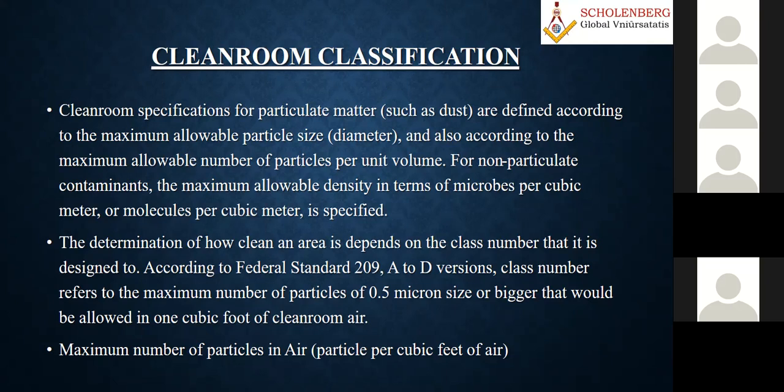We have designations, like for example, when you come to refrigeration, we have a refrigerant. How do we have a refrigerant number? We have a certain prescribed designation formula. Like if you see R11 or R12, basically it is a chemical formula, chlorofluorocarbon, dichlorodifluoromethane. These are derivatives of the methane group, CH4, in which two hydrogen atoms are replaced by chlorine atoms. That's what the chemical formula is, CCl2F2, like that.